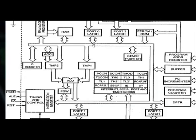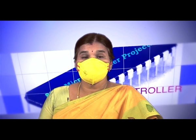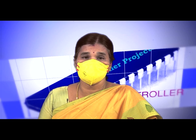That is a special feature in 8051, and when the controller wants to communicate with the external devices, it can communicate only via the accumulator. And when the controller accesses data from the memory, either the internal memory or the external memory, it can do so only via the accumulator. That is why the accumulator is called a special function register, one of the special registers to perform the arithmetic and logical operations.